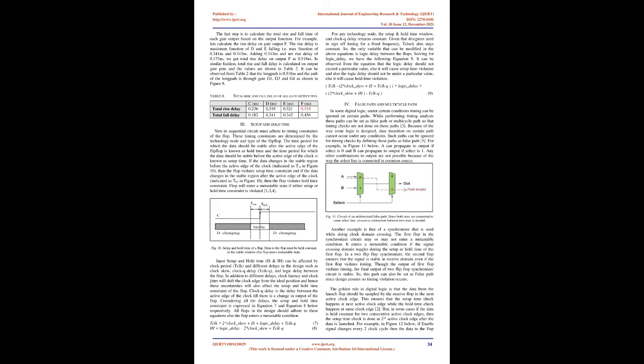Thirdly, we must calculate the relation between rise and fall function of output to the rise and fall characteristics of the input. As observed from the truth table of the NAND gate shown in Table 2 below, it can be concluded that the output Z rising is a maximum function of input A falling and input B falling, and output Z falling is a maximum function of input A rising and input B rising. This is shown in equation 5 and equation 6 below.